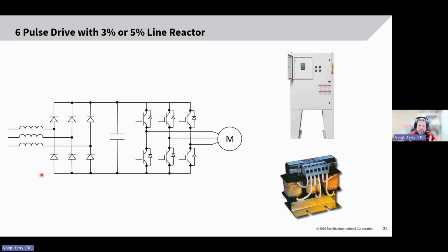For certain applications, if you know that you have some bad voltage, that would be something to consider, definitely. You could also potentially consider MOVs, a different type of voltage protection device instead of a line reactor. So there are a couple components that could help protect against voltage transients with the WC1.